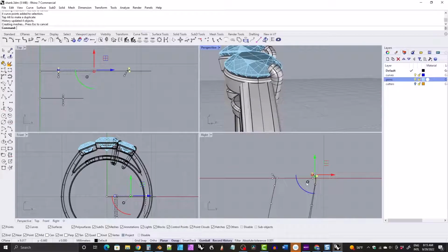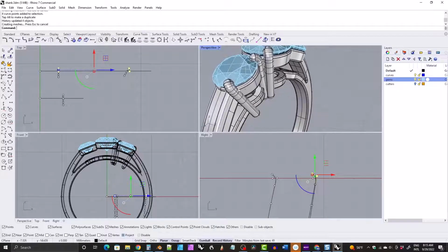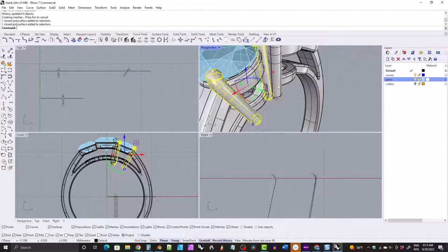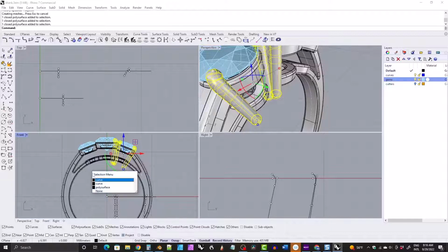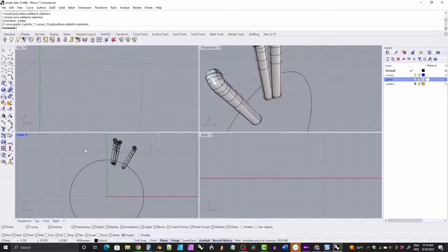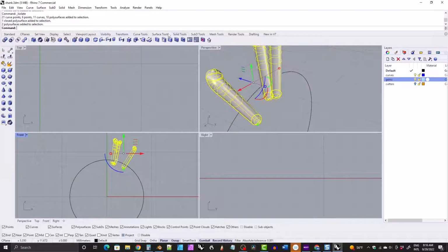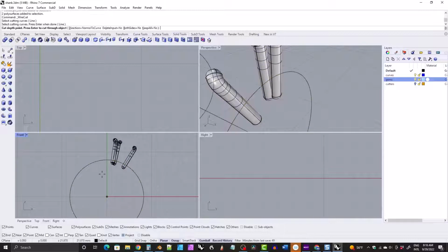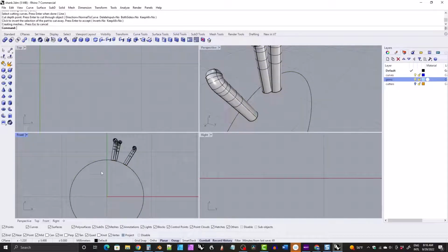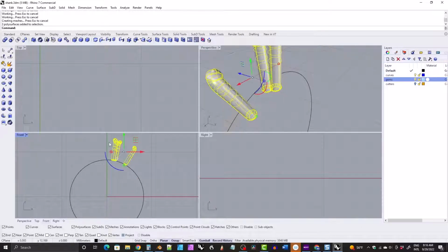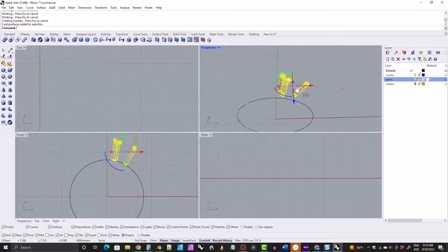Now what we would do is take the bottoms off again with that sizing circle. We'll select the prongs and wire cut the sizing circle off of them, then fillet the bottoms of all the prongs, and then mirror them over just like before in both directions.